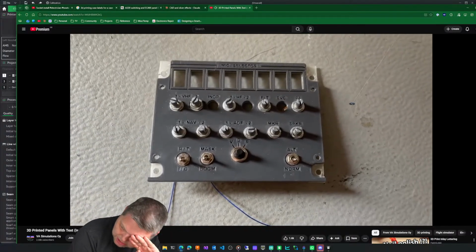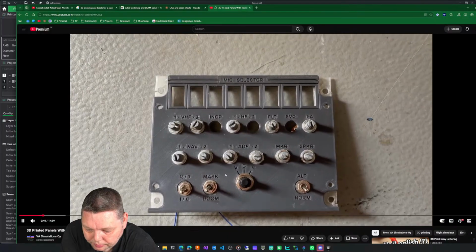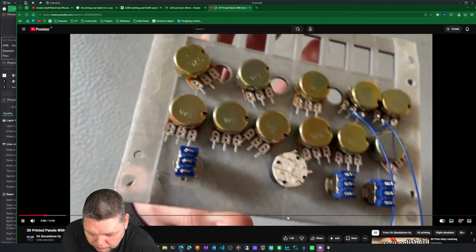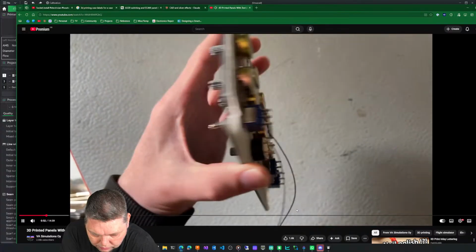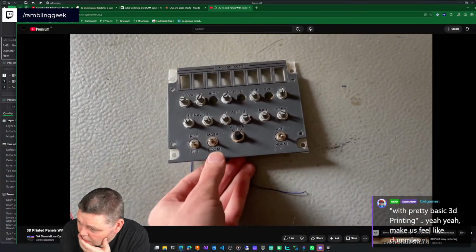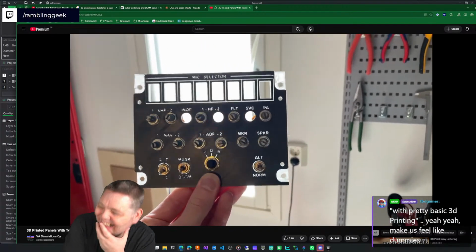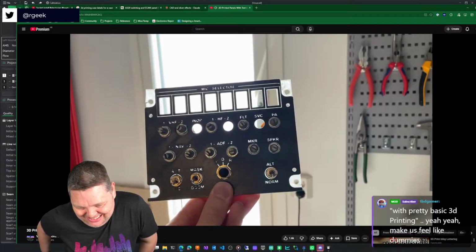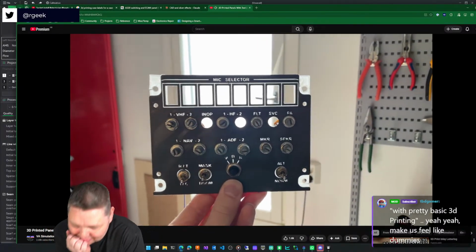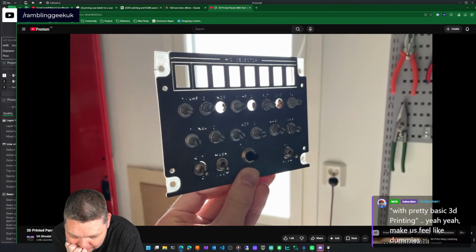Here's the old panel design, and you can see the text is kind of below the panel surface, and this allows it to be backlit, and it's very simple to make, but this causes it to be not very visible at an angle or if the backlighting is off, and it becomes especially a problem during day operations. Or if you're looking at it from the seat quite on the side and not straight at the top.